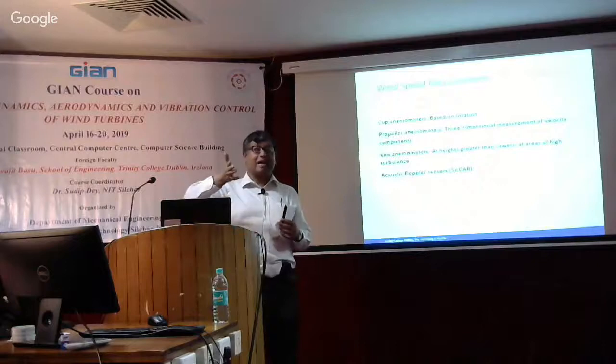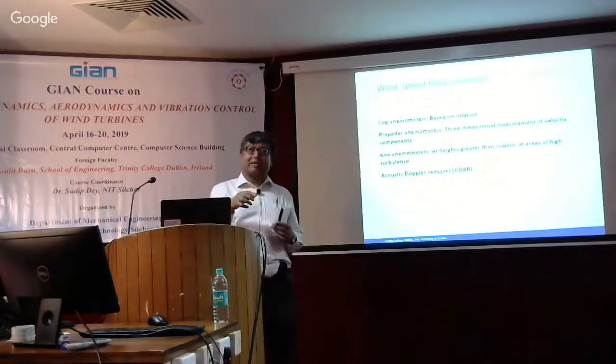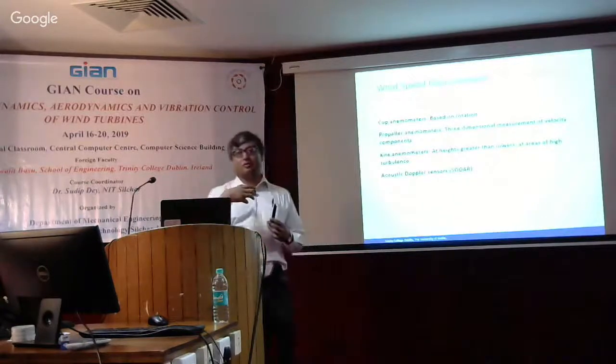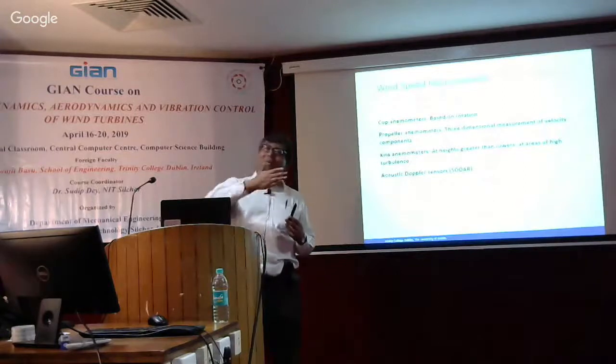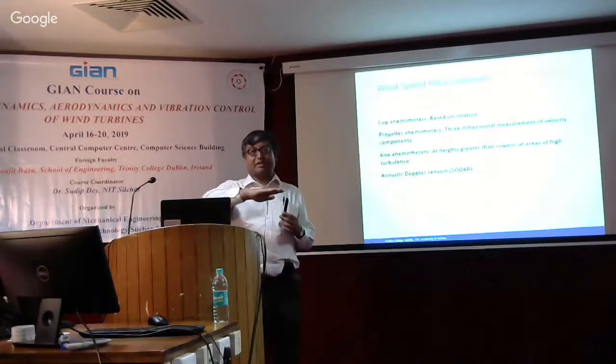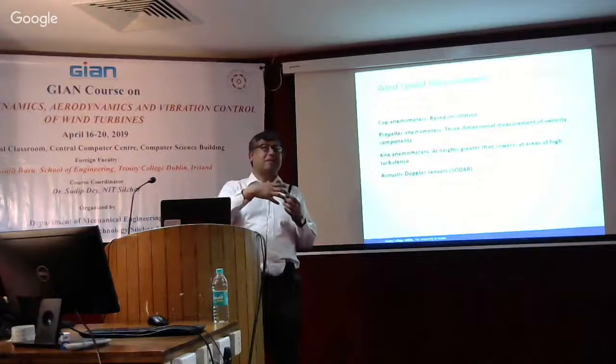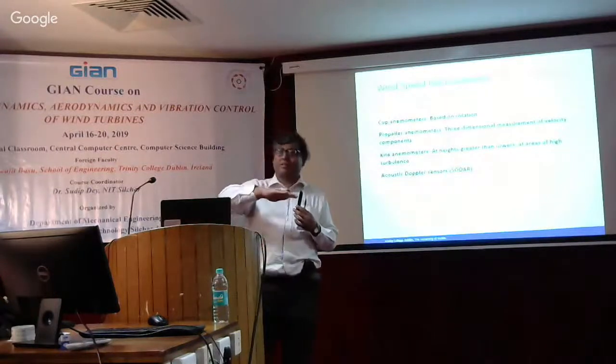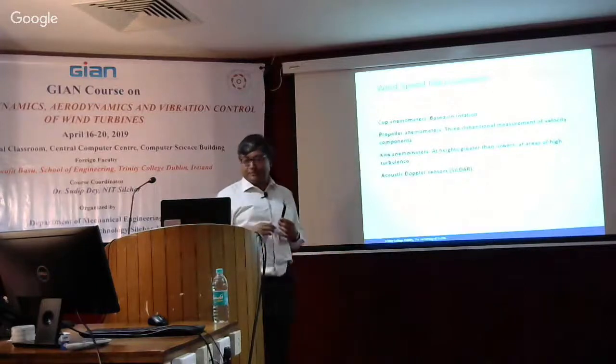And based on that, I can react in advance of the wind coming to the wind turbine so that I can appropriately pitch my angle of attack. Because by the time the wind comes, if I pitch my angle of attack, it's too late to do that. I have to do that in advance to account for the effect.